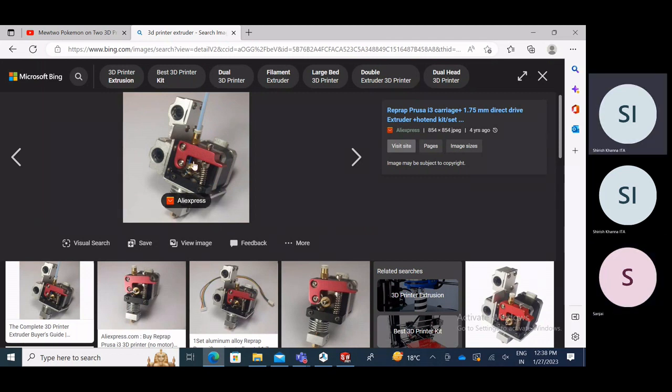So what we have to do is preheat our extruder first, so that the material inside melts easily. That's why we preheat it first. Similarly, don't directly shut down our 3D printer. First, we have to give the extruder the cooling period, so that the material inside goes outside from the nozzle, and the material stuck here is cleared so that this portion will be clean. Otherwise, extruder pins are also available to clean the extruder and the nozzle.